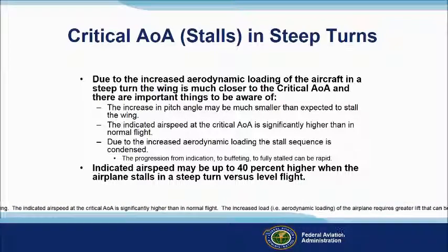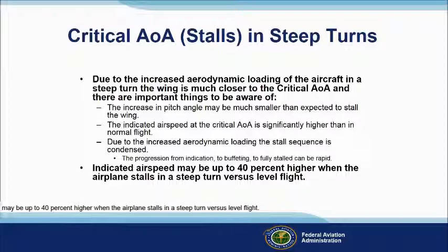The increased load, i.e. aerodynamic loading, of the airplane requires greater lift that can be created by increasing airspeed or increasing the AOA. Due to the increased aerodynamic loading, the stall sequence is condensed. The progression from indication to buffeting to fully stalled can be very rapid. Indicated airspeed may be up to 40% higher when the airplane stalls in a steep turn versus level flight.